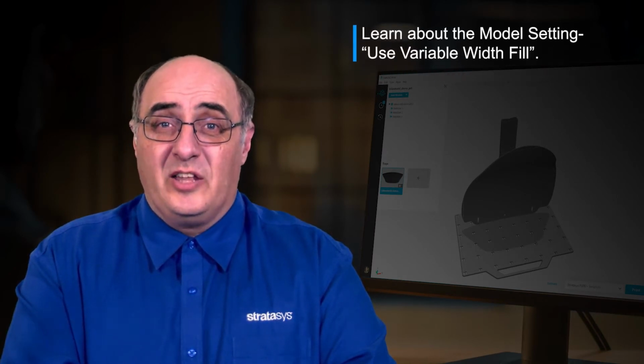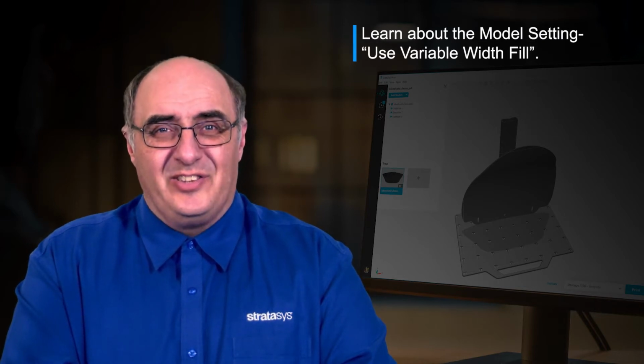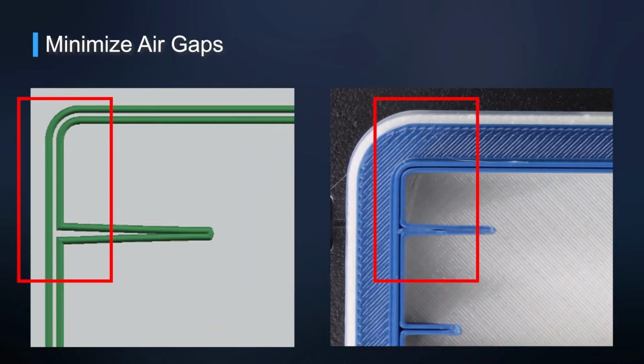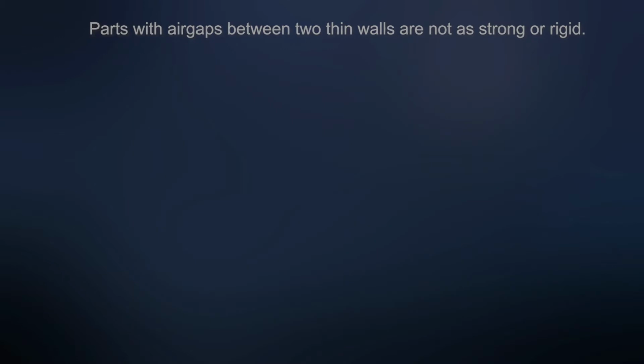In this video, I'll discuss the model setting Use Variable with Fill. Let's get started. This feature is useful when you have air gaps between two walls that are too small to fill with an infill raster or a contour. Parts with air gaps between two thin walls are not as strong or as rigid as solid parts. This can result in a part that is easily damaged when force is applied to it.